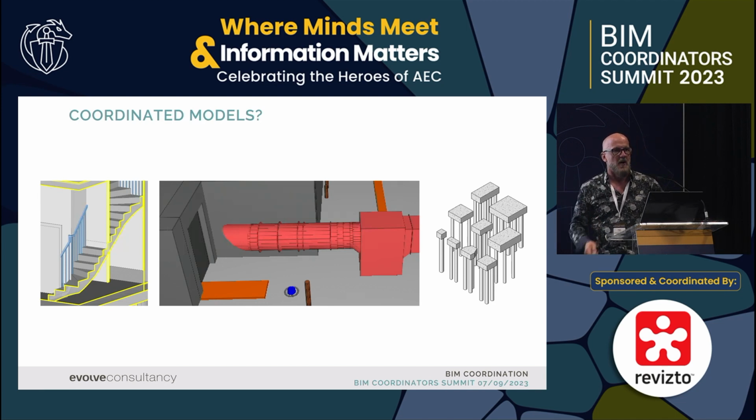What they'd picked up on as clashes, any structural engineers here will be going, oh, duh, were piles with the pile caps. And they picked all those up as clashes. And you kind of go, hold on, they have to clash. That's important because if the pile doesn't sit in the pile cap, it's not going to work. So you've got to understand more than just technology when you're doing this role. You've actually got to understand what it is you're trying to achieve rather than how you're trying to achieve it.